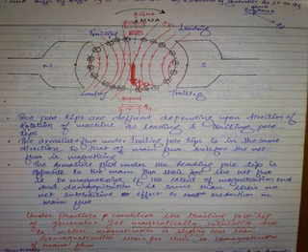Previously, 2 Webers of flux is flowing uniformly distributed. Now, 2 Webers of flux is flowing in this manner. Is there demagnetization? No. No reduction in flux. Magnitude is the same. But what happened to the axis? Shifted, disturbed, distorted. But let us say the decrease in the flux is 1 Weber, the increase in the flux is only 0.9 Webers.